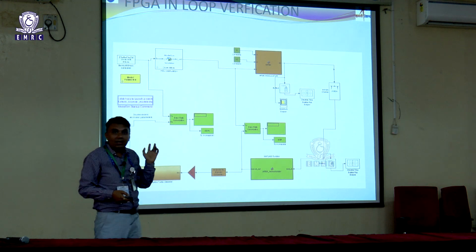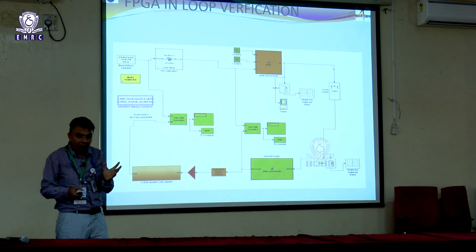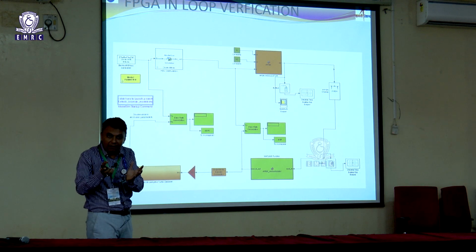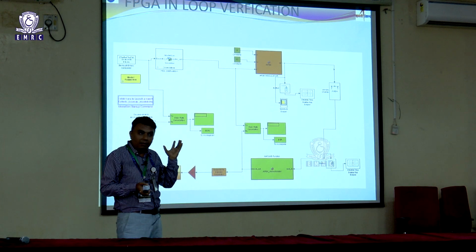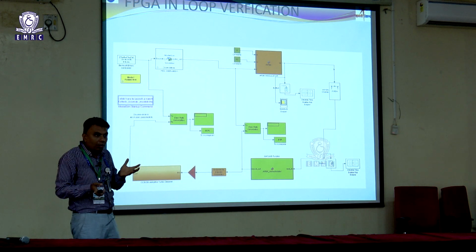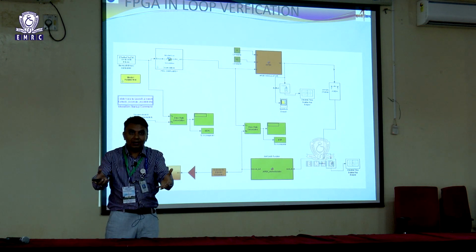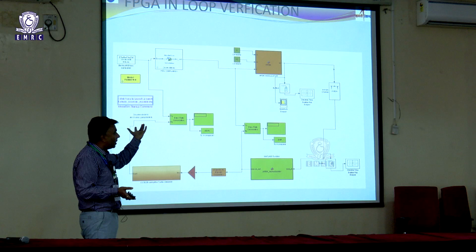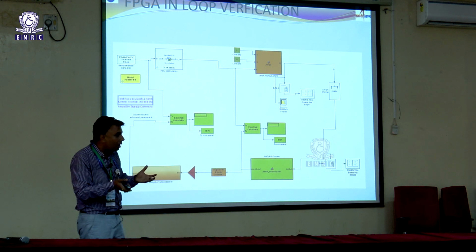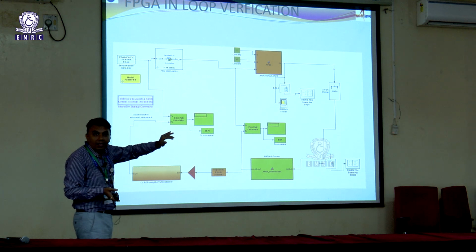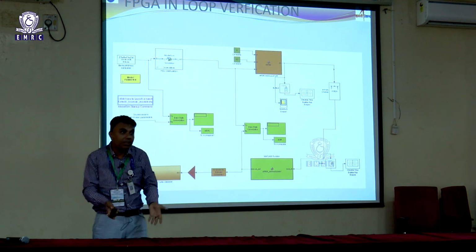For the students, these are some advanced verification techniques where they can utilize limited resources but still verify their design. One is called FPGA in loop verification. This is basically given by the MATLAB team, where you have your own HDL design but you don't have the source and sink hardware with you. You have only Simulink and ModelSim for verification. What you can do is bring your HDL code into the Simulink environment itself, and in a closed loop you can verify your HDL code without having an FPGA board.